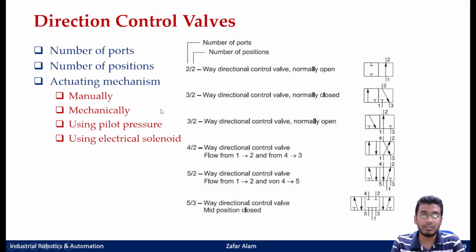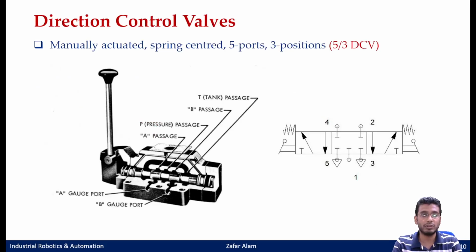Okay, now again I will give you a more detailed look here of how a valve is manually actuated, mechanically actuated, pilot pressure actuated, as well as by electrical solenoids. See the direction control valve that you can see on the left. What is it? It is manually actuated. Why? Because you have a lever to actuate it.